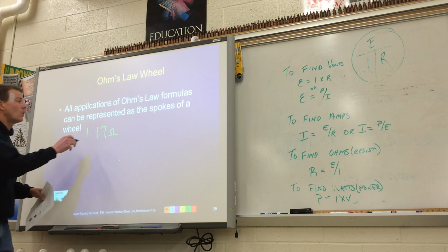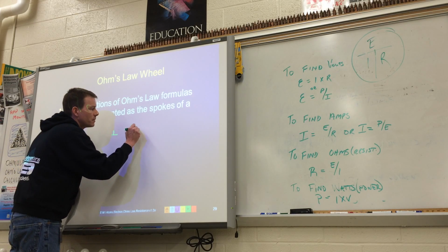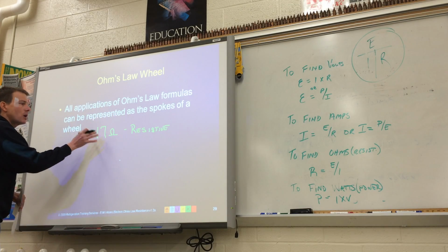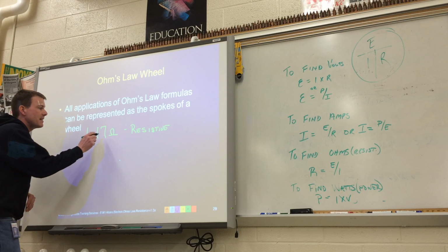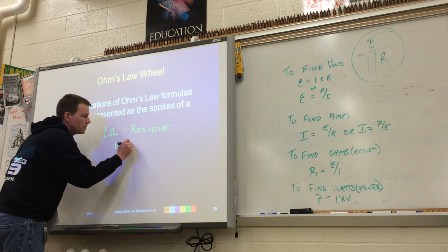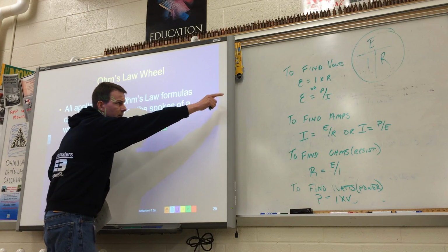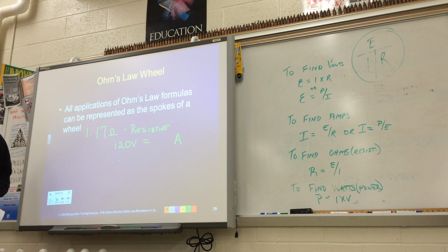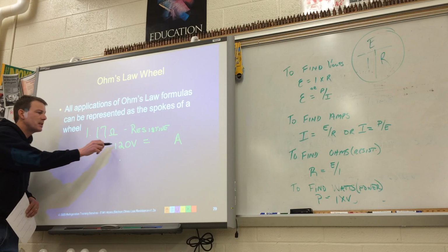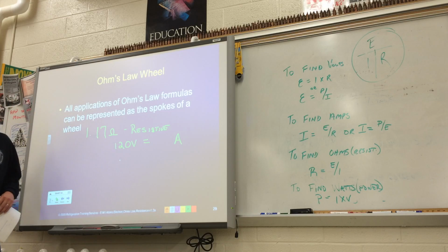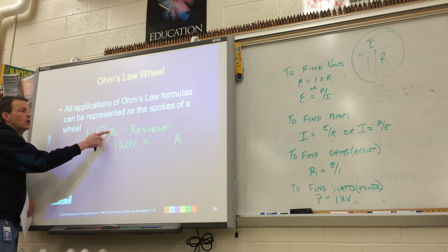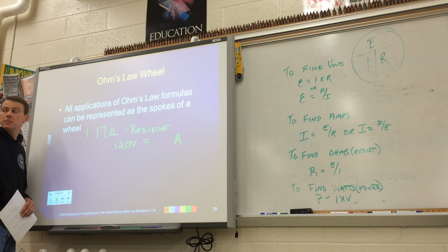Okay, so for number 1, this is a resistive load. There's going to be 3 different types. Ohm's law will work for a resistive load. So if I gave the power 120 volts, using the E I R over here, what would the current flow through the wire be, or our amps? In other words, if I clip the amp probe around that wire, it should match up with the number I get from using these 2 numbers with Ohm's law. So you got the E, that's 120 volts, and you divide it by our R, which would be what? What's your math there?